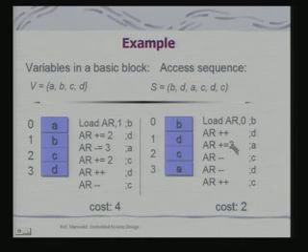The basic point is that I load AR, and then if I increment by 1, I go to D. For going to A, I need to increment by 2, no doubt about it, but subsequently it is all either decrement by a single value to go to C, decrement again by a single value to go to D, and then you increment it to again come to C. So, here all these AR decrementations as well as incrementations will take place in parallel using the address generation unit. So, you can see this layout is more efficient.